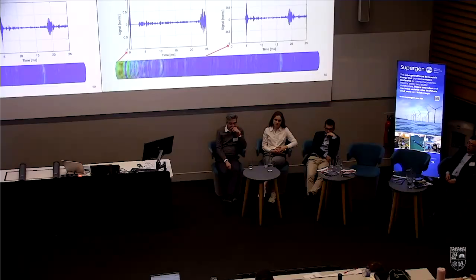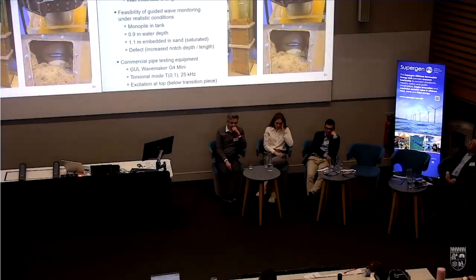Now, as ever, finite element simulations obviously simplify the problem quite a bit, which is why we did some experimental monitoring. Obviously, for a feasibility study, we couldn't quite go out to an existing wind turbine, so we developed a prototype in the lab, but tried to scale it as well as possible to match an actual wind turbine monopile. So we went for a scale of about 25:1, which gave us about a 2 meter monopile, which we made in a similar method as a real monopile.